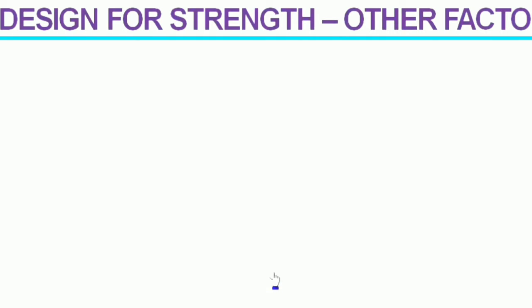Here we will do the same design as we did in the last section, but by considering many other factors which will come into the picture. So, a more realistic approach. The first factor is dynamic load on the gear. As gears are rotating, you can hear some sound from the gear. This is because gears are clashing with each other due to a small gap in between, and this effect will increase the load on the gear more than its actual value. That is known as dynamic load, and there is a factor to represent that, Kv. It will be a function of pitch line velocity.